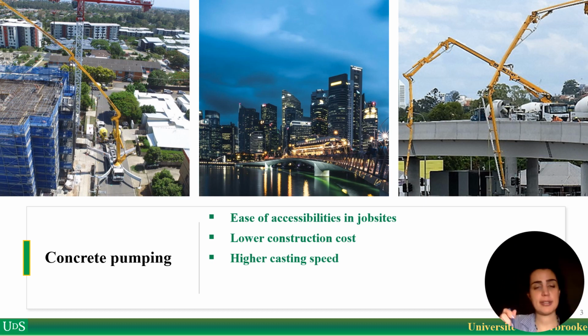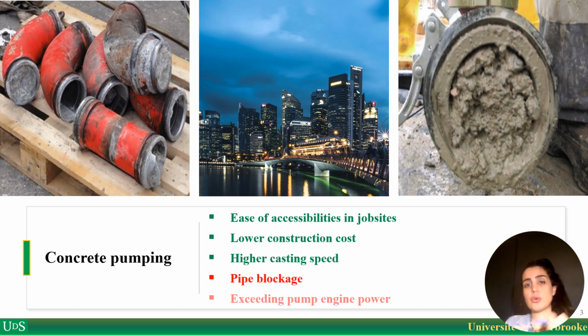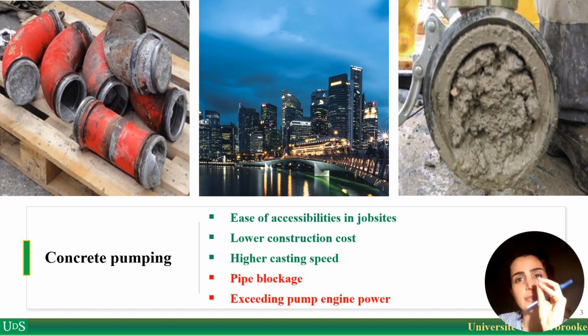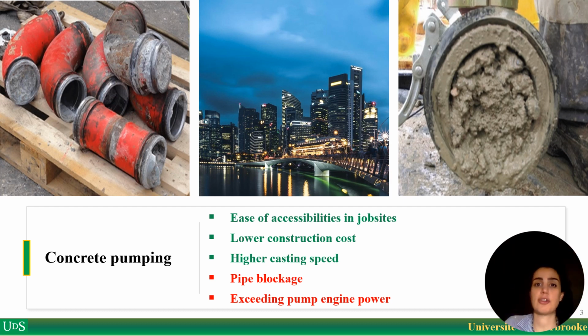Imagine you prepare everything, but suddenly the pipe blocks. So you need to go and fix that point of the problem. But sometimes you need to restart from the beginning, and you can imagine how much it may cost the construction industry. So what I want to say is it's very important to reach a good prediction of the behavior of concrete pipe flow, or a good understanding of the pressure loss of concrete during the pumping process.